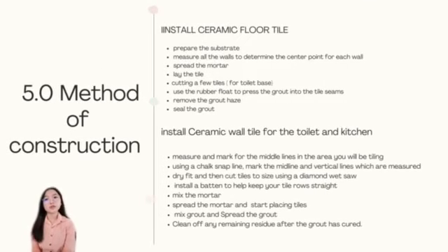Next, we need to install the ceramic floor tile. The first step, we need to prepare the substrate, and second, measure all the walls to determine the center point for each wall. Next, spread the mortar, lay the tile, and also we need to cut a few tiles.